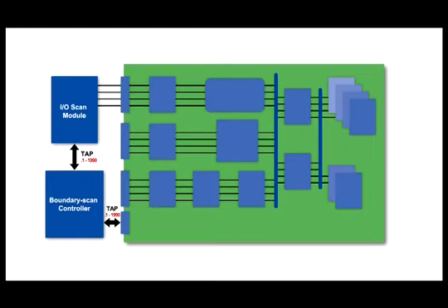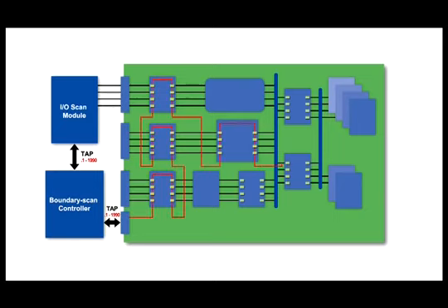In this diagram, the boundary scan register is shown for the .1 devices. .1 devices are cascaded by connecting the TDI and TDO signals to form a scan chain. A single board may contain one or more chains, providing high-speed serial access to the test resources on the PCB.